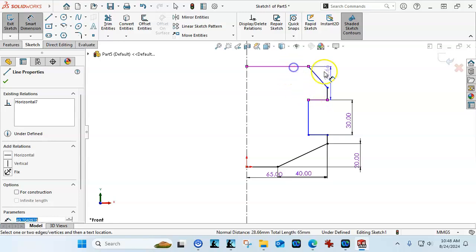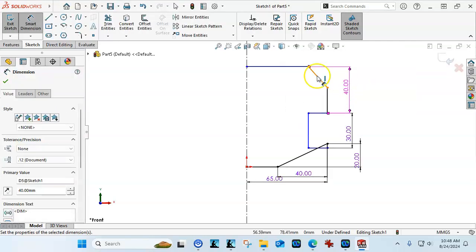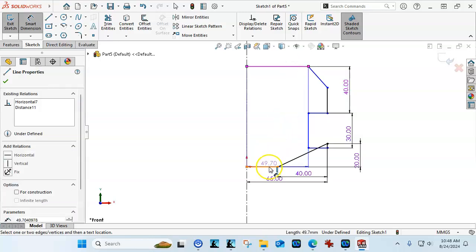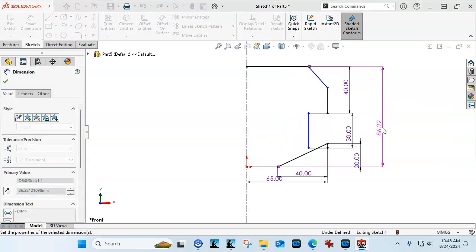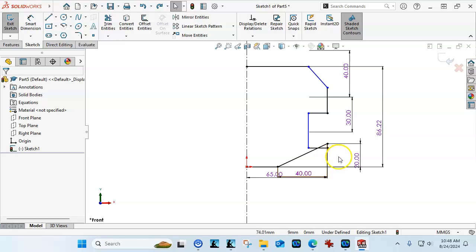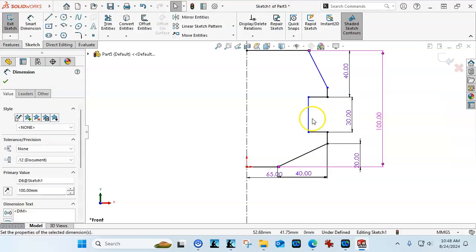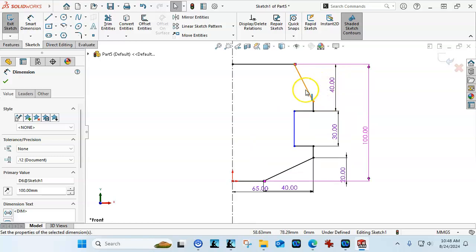And let's see which one is going to cause me to go over defined. I guess not. We're going to go between the two objects and give it the 100, and that's going to stretch it out. So let's undo that just quickly. I'm going to show you that as this moves around, it's not uncommon for the sketch to overlap, have some different things going on. Try to pay attention to what it's doing, why it did it, and then it's a lot easier to correct for it.